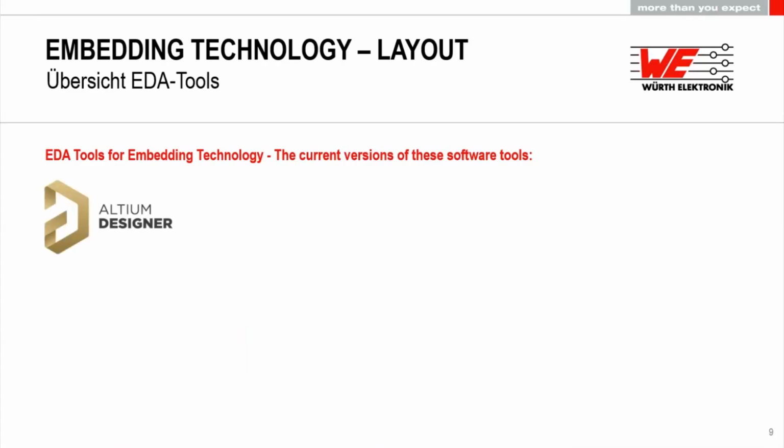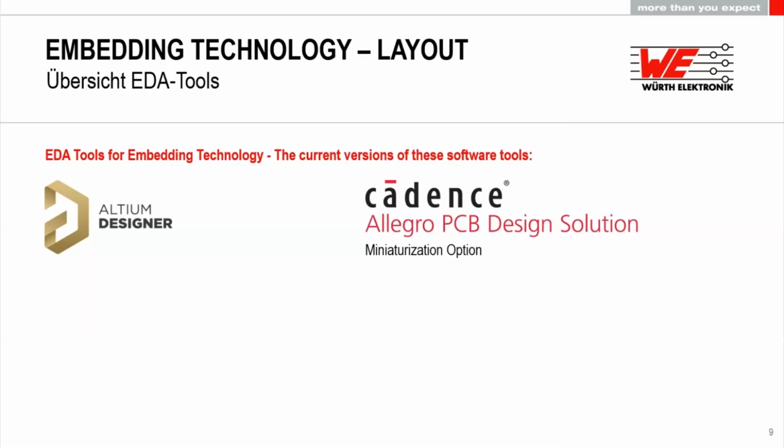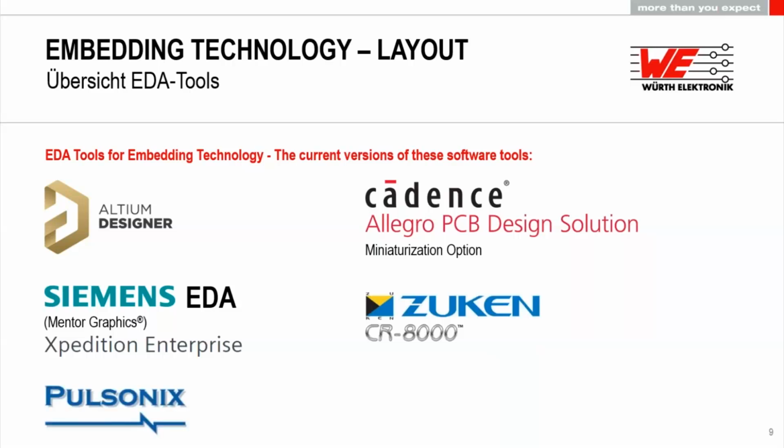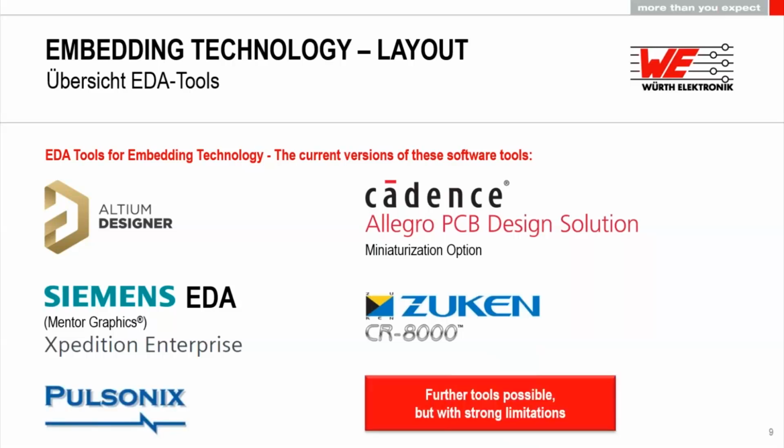So we know that Altium Designer and Allegro from Cadence with the miniaturization option offer the capability to create boards with embedded components, as well as Expedition from Siemens EDA, formerly known as Mentor. They renamed themselves at the beginning of this year. Then we have Zuken with the CR-8000 package and Pulsonix. There might be other tools which offer this as well, but those 5 are the ones we already know, where we know that they have a certain capability to move components, for example, onto inner layers.